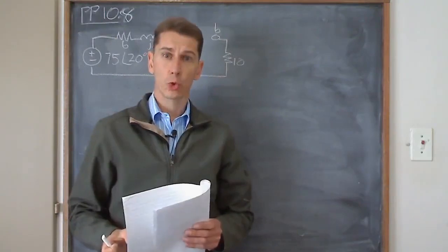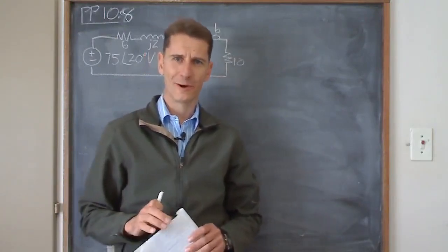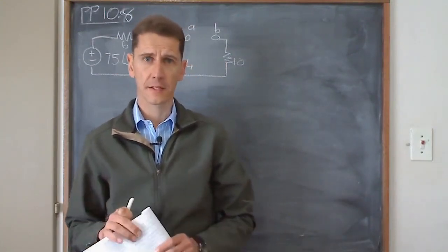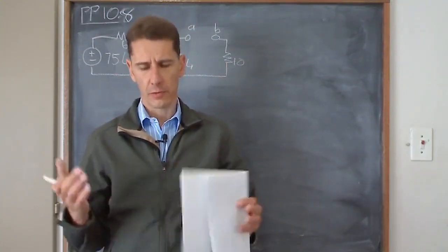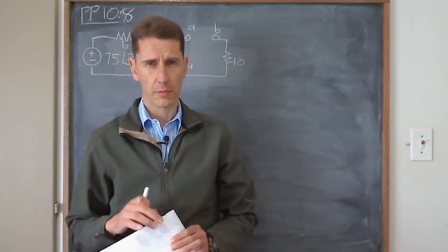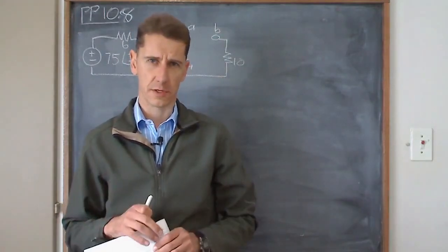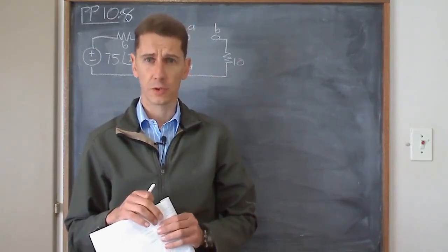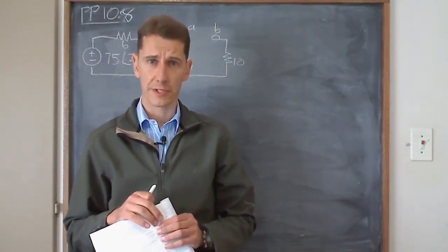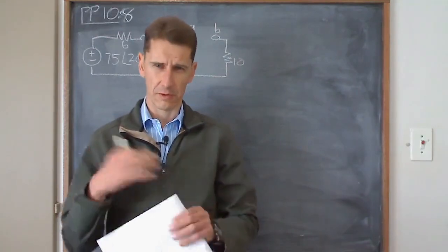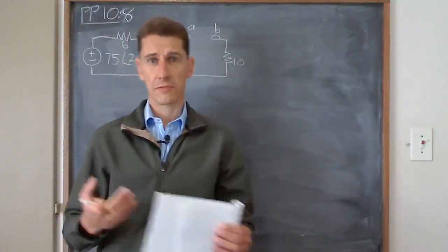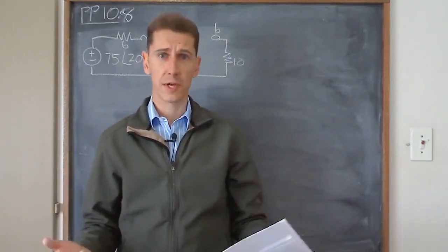We're now going to look at Norton and Thevenin equivalence. Now, I know you guys have this phobia or this mental block against it, but hopefully I'll be able to remove that for you. What is a Thevenin equivalent circuit? It's a voltage source in series with an impedance. And Norton is a source transformation of the Thevenin equivalent, and vice versa. So if you have the Thevenin, you have the Norton. If you have the Norton, you have the Thevenin. It's just a source transformation away.